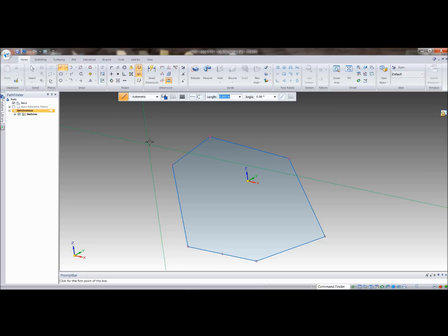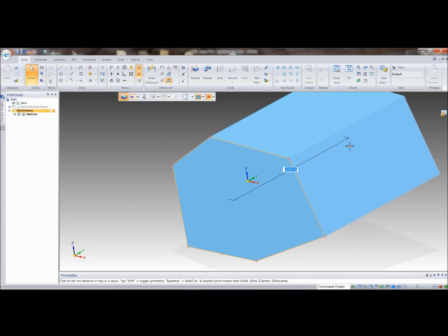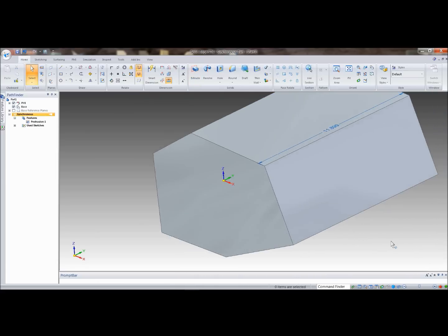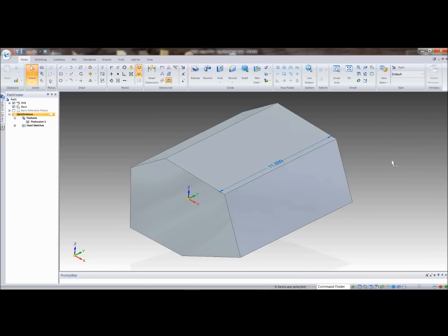And that's been around for a long time in the 2D environment. But in ST6, they give us the ability to do goal seeking now in the 3D environment. So I've created a Solid Edge synchronous part here by creating a region, and I'm going to go ahead and extrude that back a distance. And this is kind of a generic application. It may not seem that it's a real-world application. It's kind of made up. We make these examples up to try to drive home the ideas and the concepts within these tools, and leave it to you to apply them to a real-world situation.